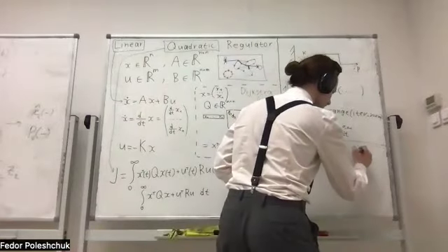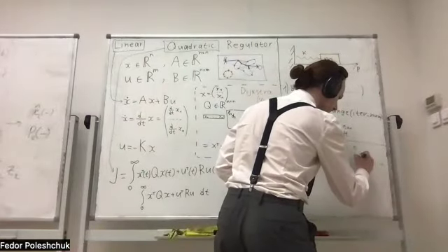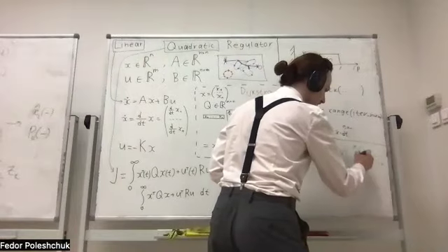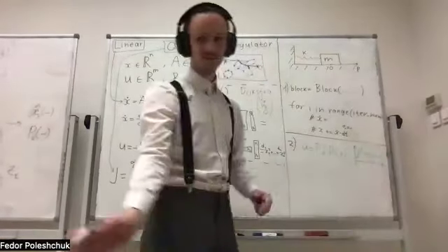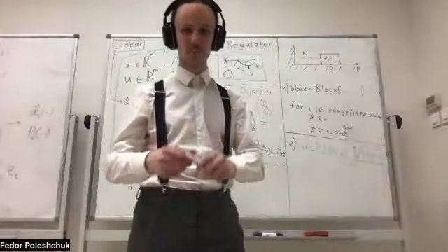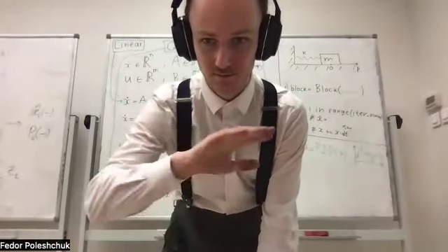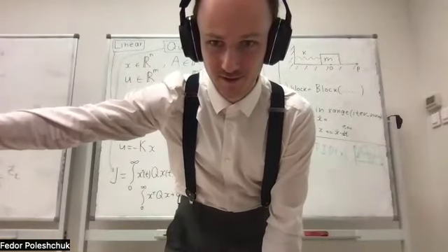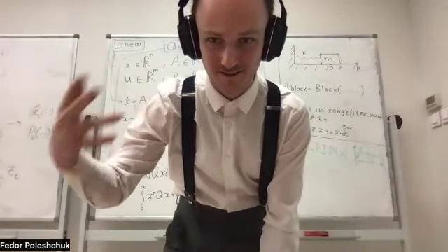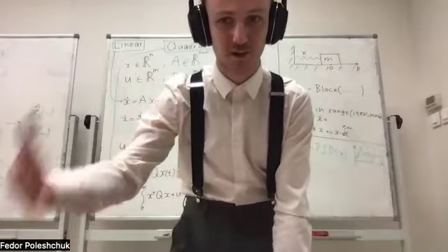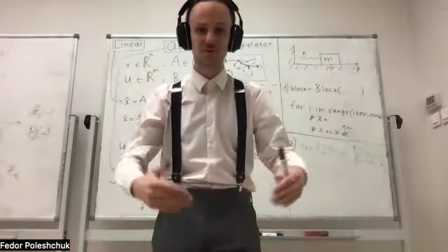Observe all those overshoots, this kind of behavior, diverging behavior, whatever. Try setting positive differential feedback. The system will just accelerate towards infinity, but you will make sense of this behavior. So it will become clear what coefficient corresponds to what.